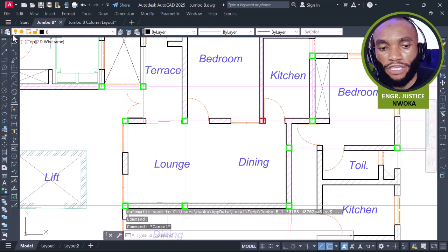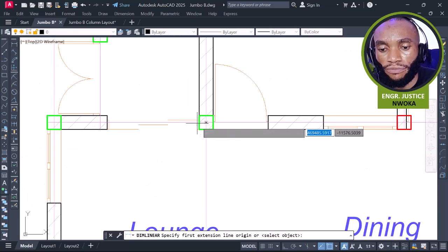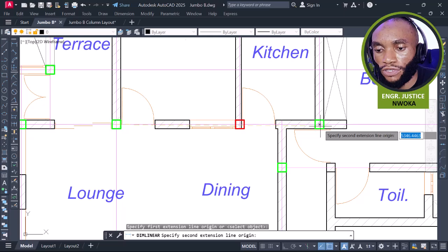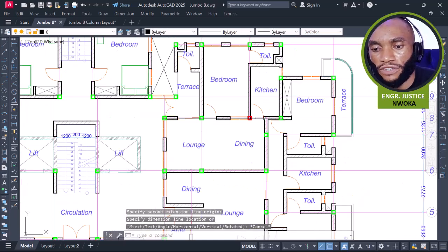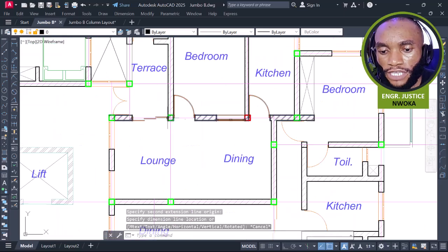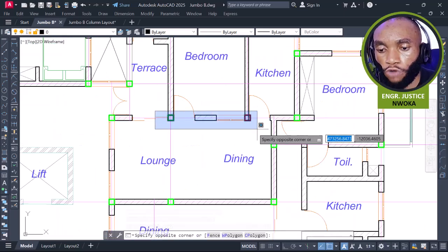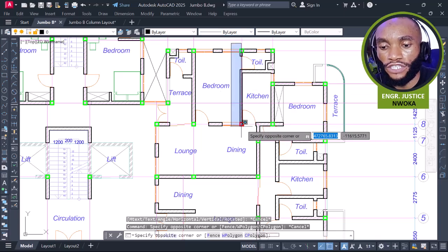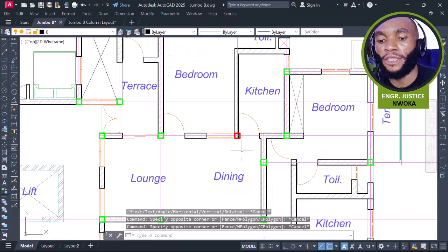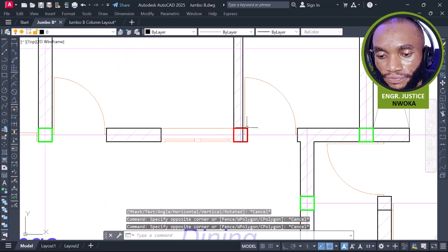I choose to have a beam from here that will run from this column to this column here, which is 5.3. Yeah, that's okay. No need for this other column here. Although this beam here will be very heavy with load, because the load coming from this beam will be resting on this particular place here. But let's leave that first for now.